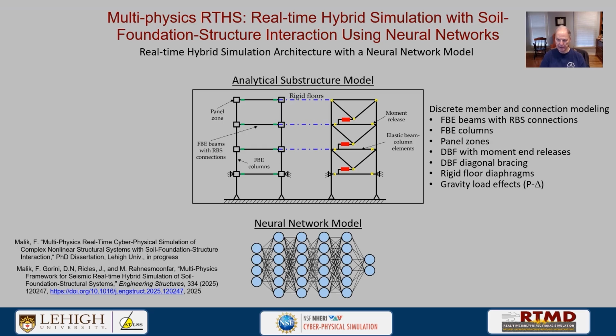We're going to model the beams with force-based fiber elements, which are going to have RBS connections. So throughout the length of that portion of the beam, we're going to have integration stations that have reduced flange widths. Again, this is documented in the publication on the lower left, Engineering Structures.